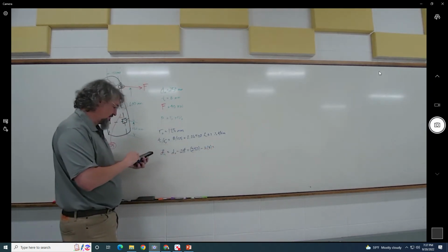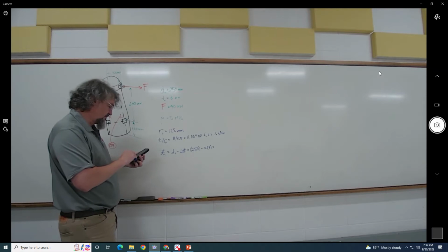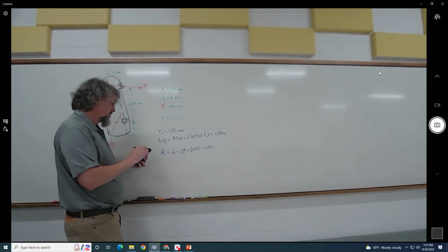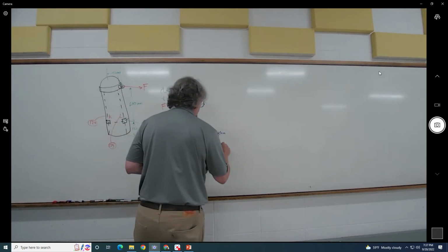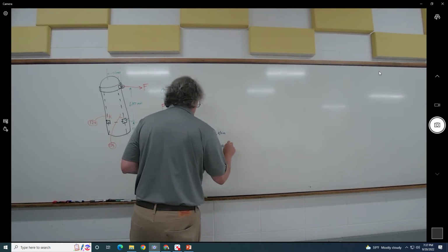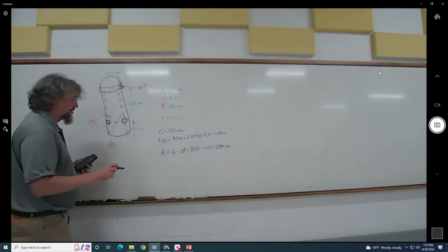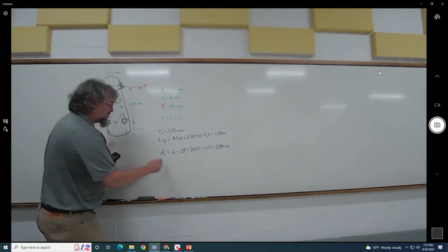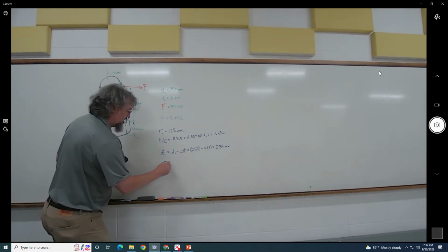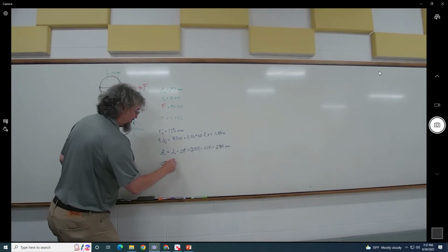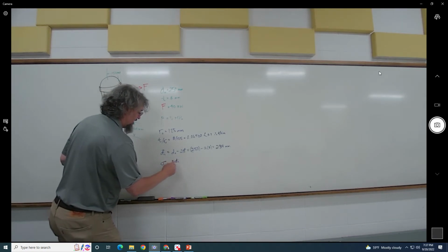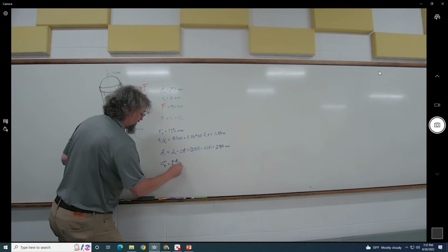I think it's 234, is that right? 234 millimeters. I'm getting tired. So we could find the tangential stress by taking P times di, dividing it by 2t.